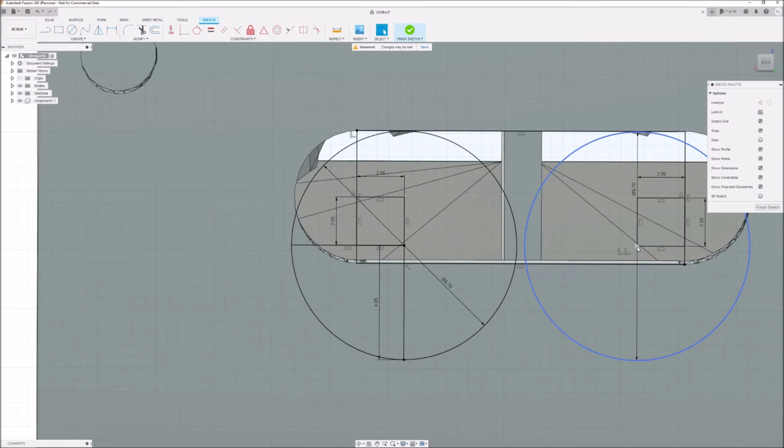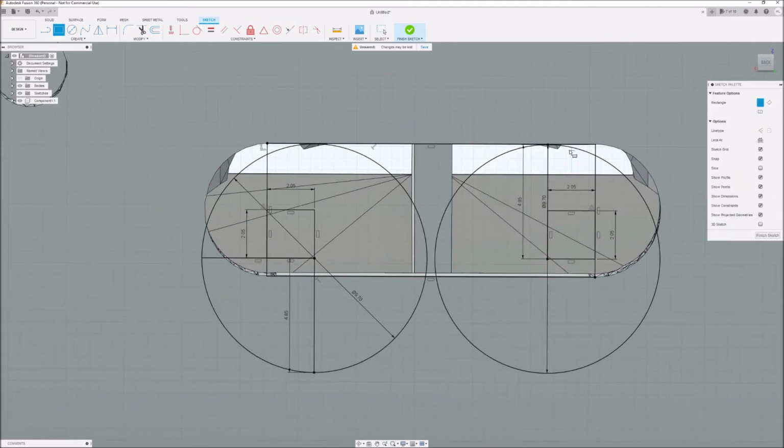I'm going to do the same over here, except I'm going to go up because I just need 2 points to draw my rectangle. Click 4.85, hit enter. Oh, whoops, that go up, yep. And now I'm gonna draw my rectangle. I'm gonna hit R for rectangle, go to this top, click and release. Now just move my mouse down here and hover until I get that square, and I'm gonna click and release. And now I got my square there.